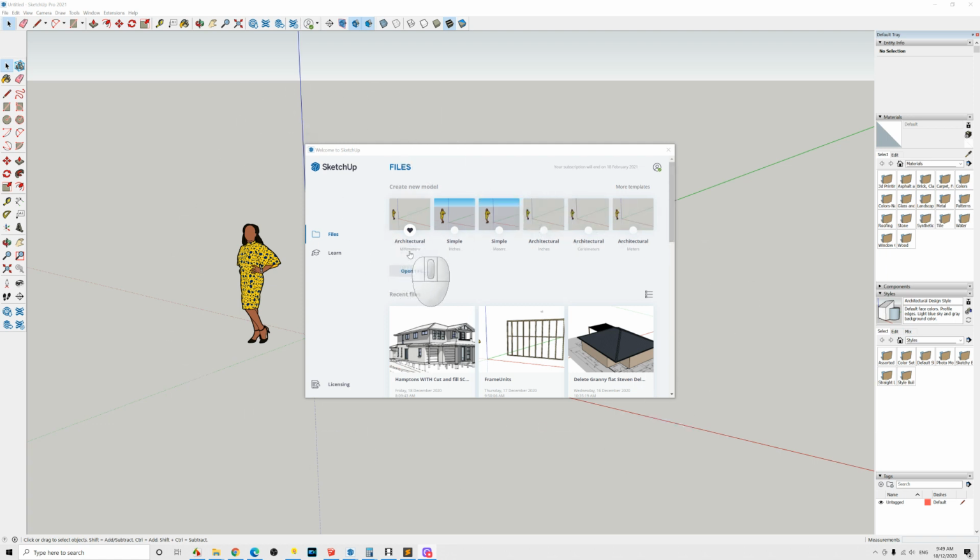I've chosen millimeters. So in Australia we actually use millimeters as our default units in the design, estimating, construction industry. However, if you're stateside in America you might be using imperial. And if you were using meters, you need to be careful. So for instance, if you're using meters but you're typing in millimeters, everything's going to be 1,000 times bigger than you actually require. So 1,000 millimeters would be a kilometer long wall if you're not careful. So millimeters is your preferred option here.